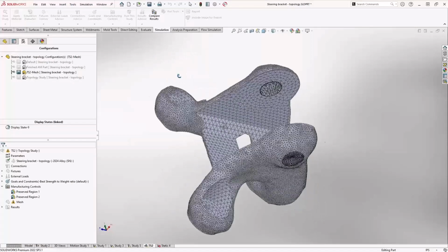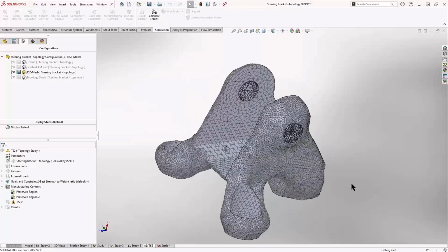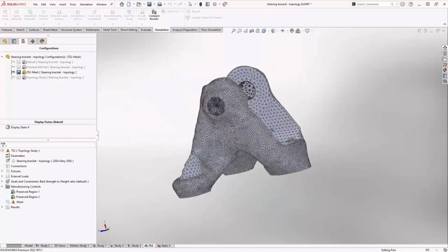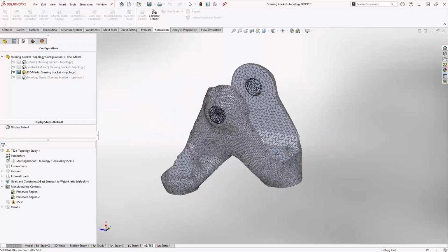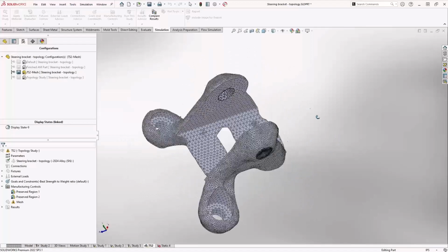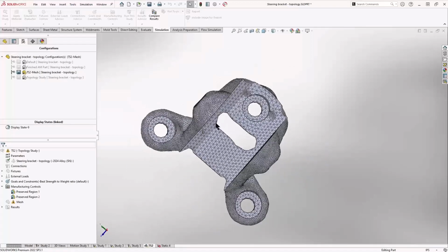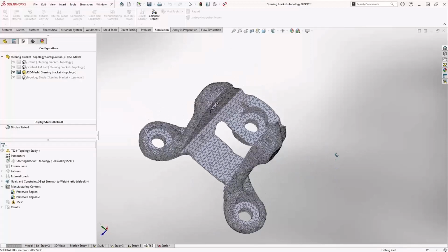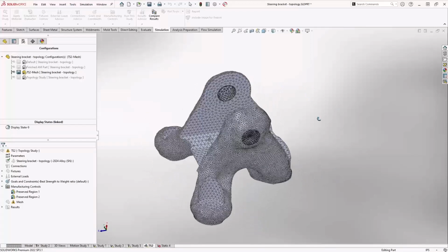This part, it is a solid body, a piece of mesh geometry, but it's solid. We can weigh it. This is called a smoothed mesh body, but as you can tell, it's kind of bumpy. This is the shape that SOLIDWORKS came up with on its own out of that C shape. You can see a bunch of material missing there in the beginning, in the middle. It's actually lighter than my original shape, my original part, but it's hard to manufacture. I could cast it, I could 3D print it, but it's going to take some work.